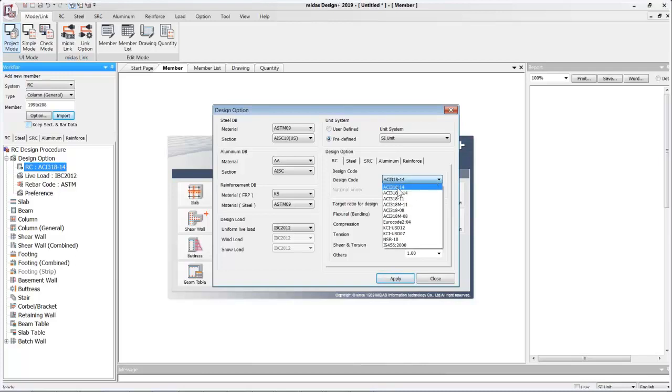It is important to note that ACI 318-14 is supposed to provide us results in inches and feet, and we have got ACI 318M-14, which provides us the output results in the form of the metric system. So this is important. Other than that, we have got older standards as well for American codes. For getting the metric system result output, I'll be using ACI 318M-14.